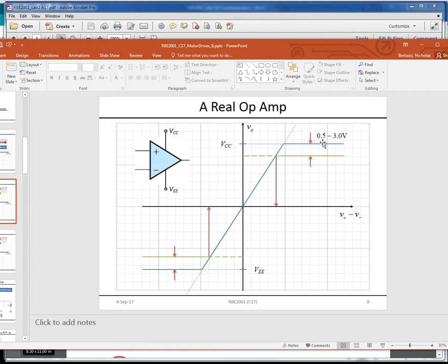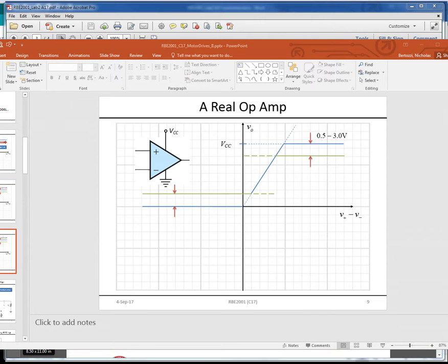So in this case, say there could be a 0.5 volt drop. So if this was -5 to 5, then you're really only able to get to -4.5 and up to 4.5 over here. Or in the case if you had one side connected to ground, so now maybe you can only get from 0.5 to 4.5, right? Once you get down to here, you can't get any lower than that.